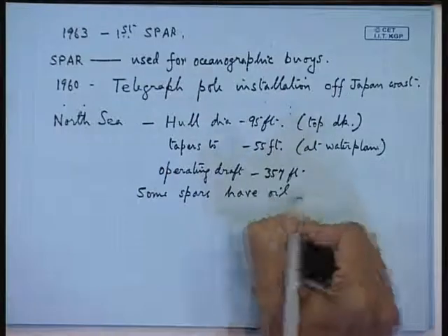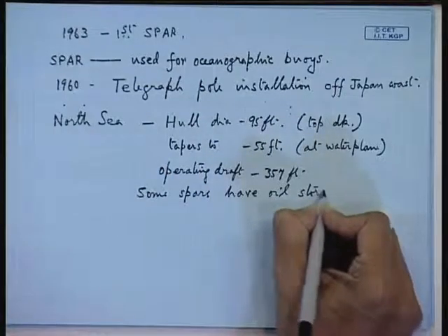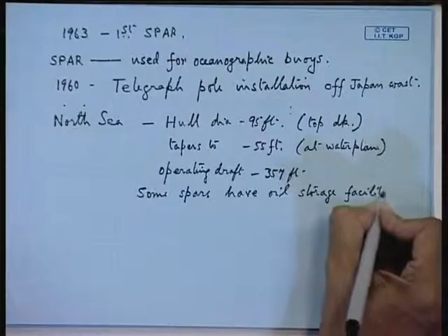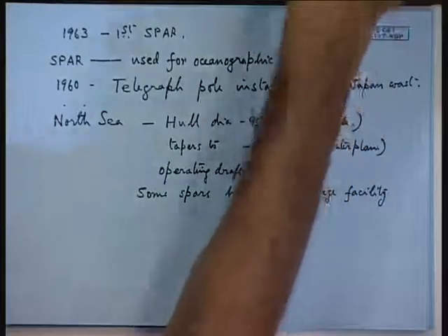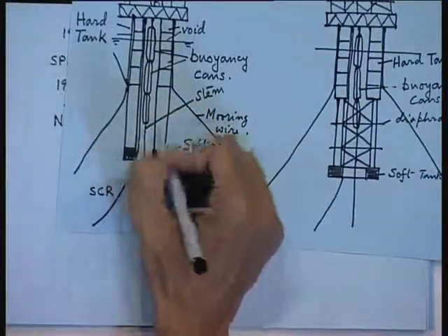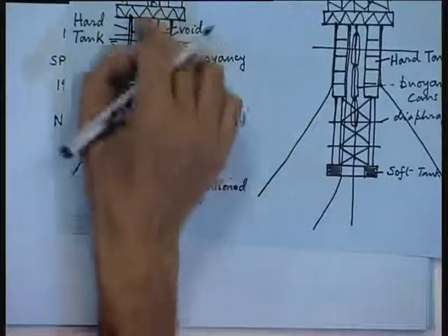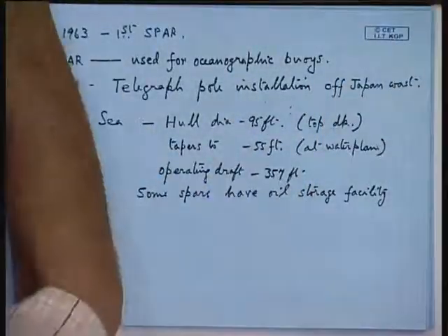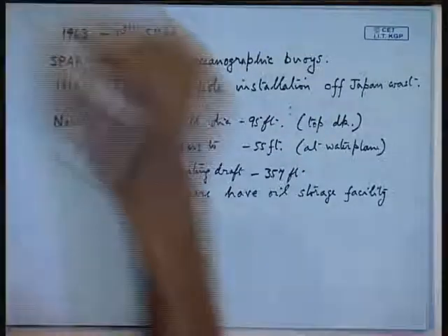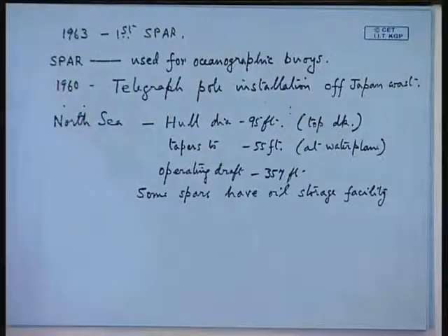Oil storage. So that means part of this hard tank, this type of spar you can have oil storage around here, okay, but don't store oil near the water plane. So that will raise your G. So that is one of the major advantages. Now here you find the spar components.